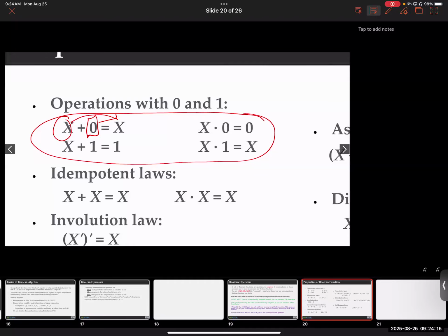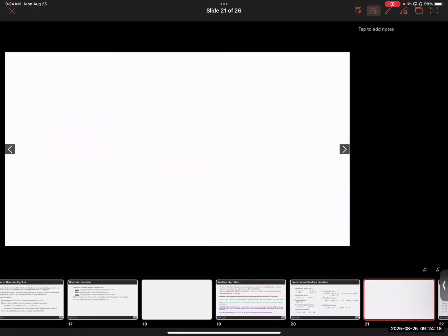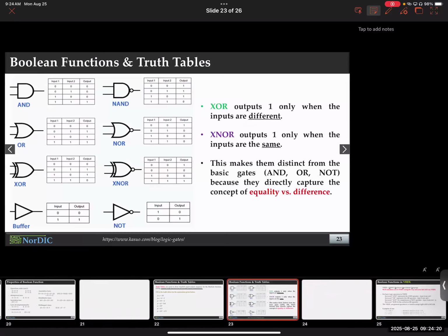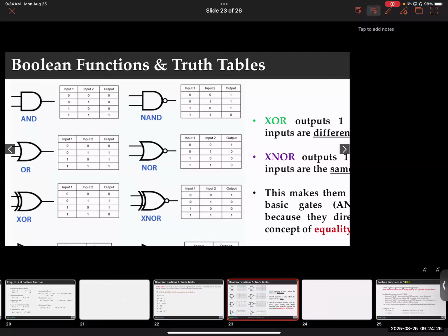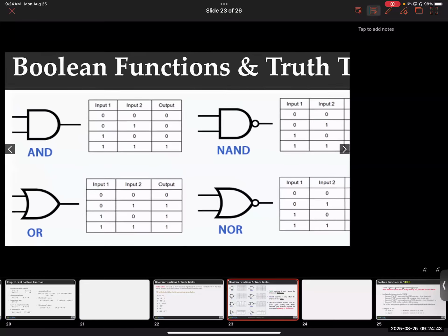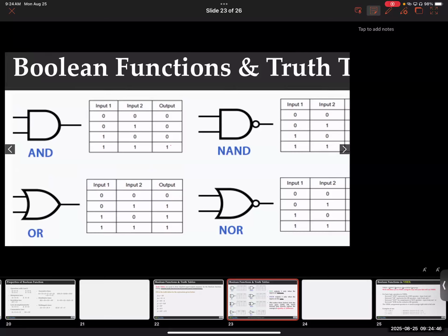No? Okay, by the way, to help you with that, let me take a step forward and show you what truth tables are. I think if we take a look at 3 truth tables, and, or, and not, everything else could be calculated. Even if you don't want to use your logic to understand why this is so, you can always use simple calculations to check whether this is right or wrong. So and, as I told you, just take a look at the truth table for and. Your output can only be 1 when both variables are 1.